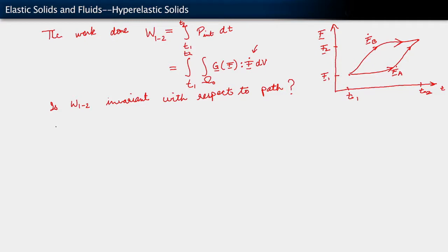To consider that, let's suppose that our constitutive function for the Green elastic solid, G(F), can be obtained as the derivative with respect to F of some scalar function of F, psi, where psi is a mapping that starts out with GL3 because its argument is F, which is a tensor, a general linear transformation in 3 dimensions.